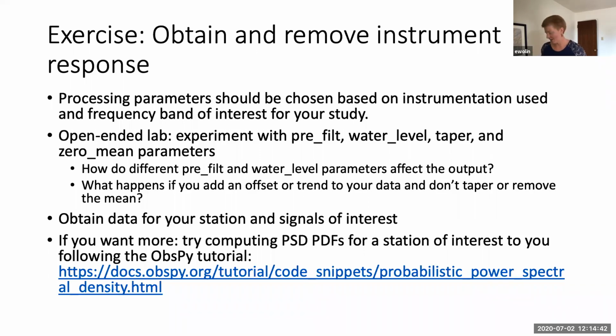For accelerometers, a lot of the time, they will put out a constant 1 sample per second stream. So you'll see LN1, LN2, LNZ, and they will only record triggered data at high sample rates. And that's because accelerometers have really high self-noise floors. And so we don't want years and years of data that's essentially just self-noise. So we wait until we have a large signal, and then the sensor and the digitizer will take a few minute snippet of that sample at high sample rates and transmit it.